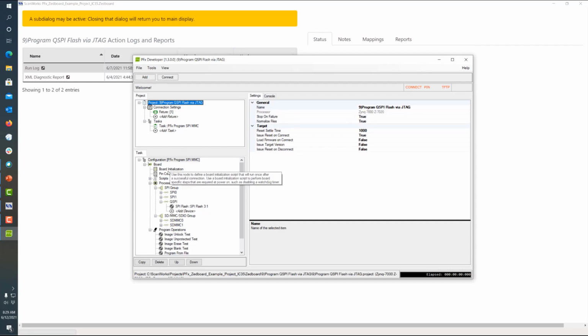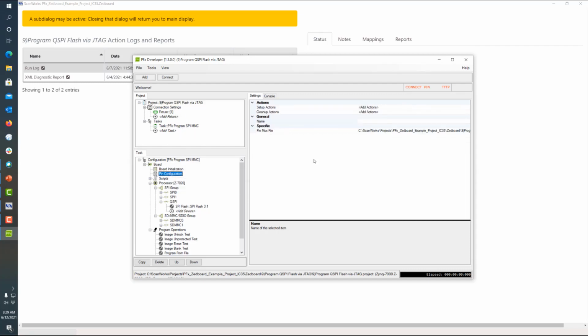One of the first steps is to configure the SoC multiplexed I/O pins. Each of the SoC vendors provide tools to initialize the SoC. The outputs of these tools are C source files. We convert the initialization source code to a script and use that to initialize the SoC directly. In this case, we're initializing the quad SPI controller.